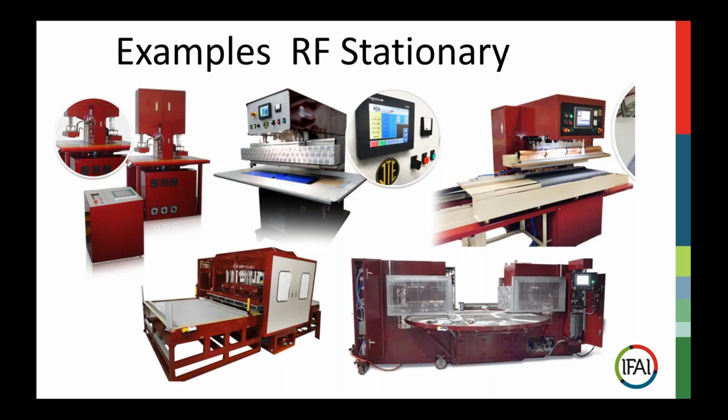On the top row, you see a double welder. This is a double station, one generator, rather small footprint RF welder, and this is commonly used in testing and small format. On one side, you can actually be bar welding, and on the other side, you can actually have a shape tool or several shape tools, and the computer keeps track of the recipes for either side.